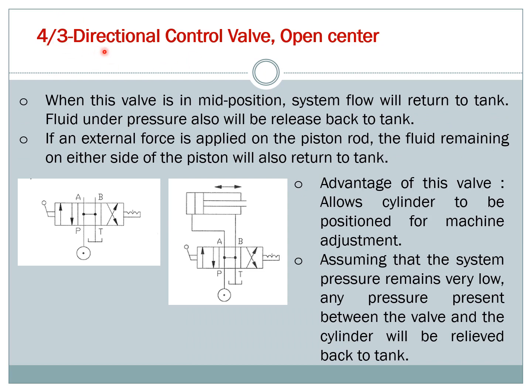The 3 direction control valve, open center. When the valve is in the middle, you can see all ports are connected, so the system will return to tank. Fluid under pressure will also be released back to tank.